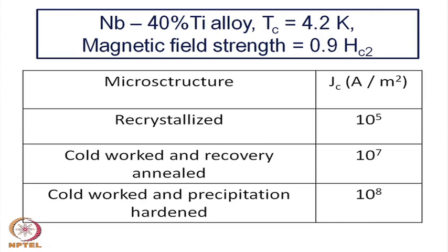With increasing temperature more and more energy is given to the system, and therefore, it is easier for the dislocations to move out of the crystals. So, by recrystallization, one actually reduces the dislocation density.